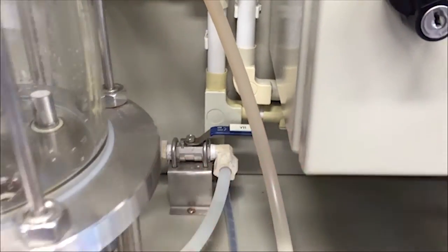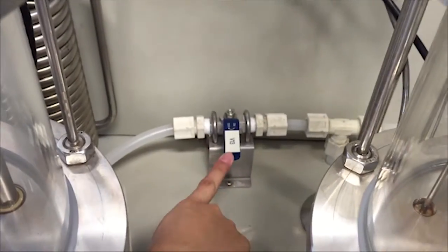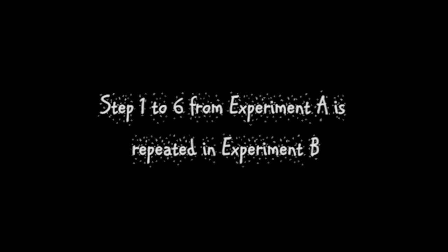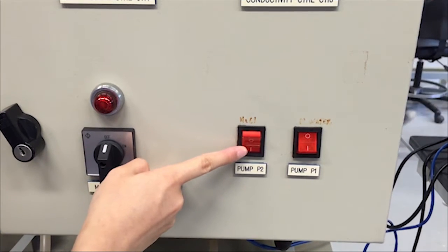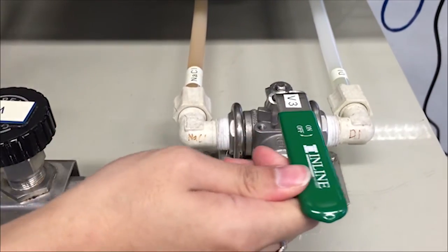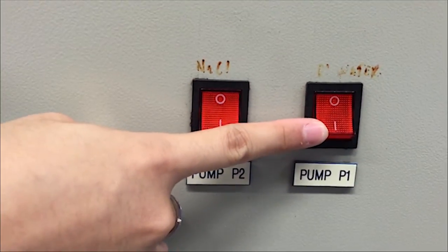In order to drain all the liquids in each reactor, valve 11, valve 12 and valve 13 are closed. Pump P2 is operated for 2 minutes and then we switch off pump P2. The 3-way valve is set towards pump P1. Then pump P1 is switched on and let it run until the end of the experiment.